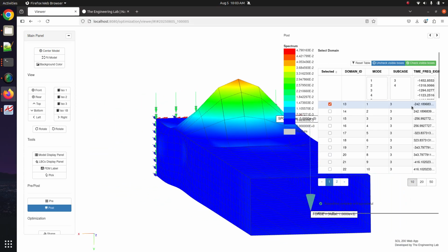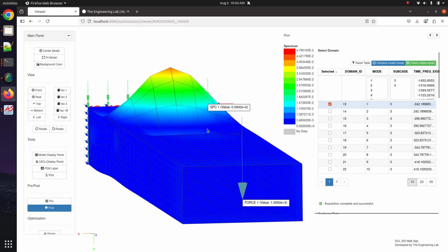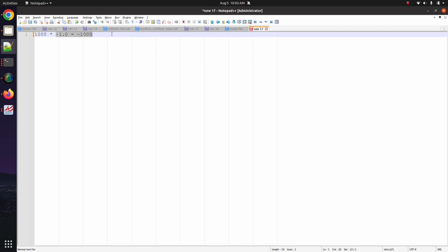So when you see a negative buckling load factor, that just means that you're reversing the loads. All of your loads are being multiplied by that buckling load factor. Actually, let's look at this. Let's copy that positive buckling load factor. So we have the force times the BLF or buckling load factor, and then we get our buckling load.